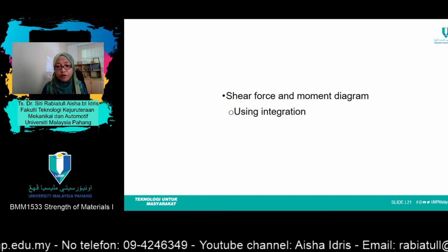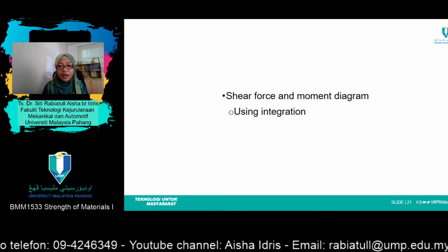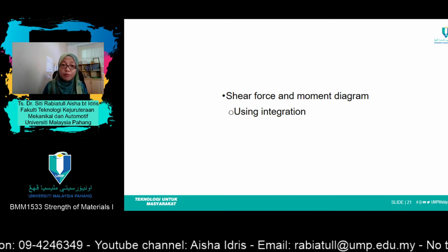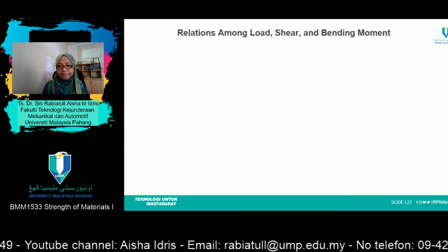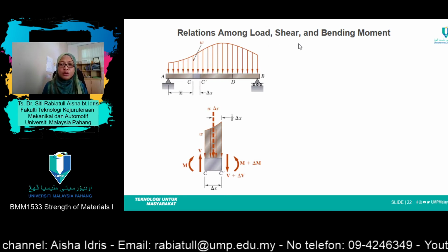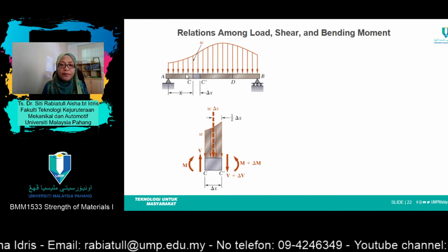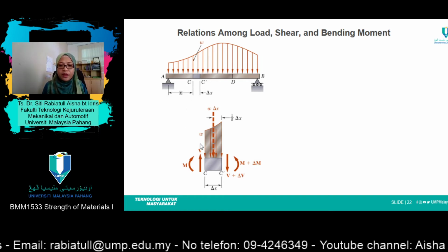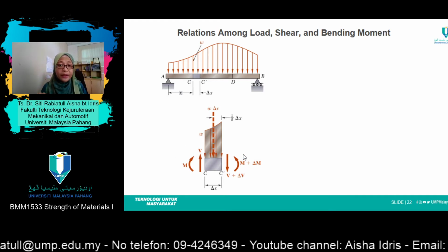Now let's move on to another method, which is using integration to draw the shear force and bending moment diagram. Okay, so this is the relation among load, shear and bending moment. By taking at this point, you see this is the sign convention as mentioned to you in the previous slide.